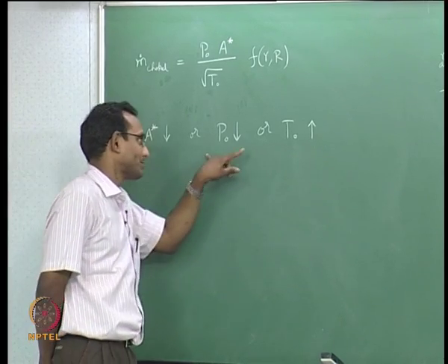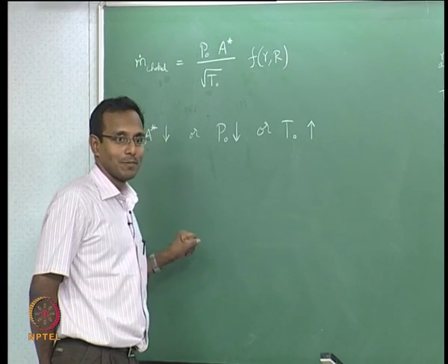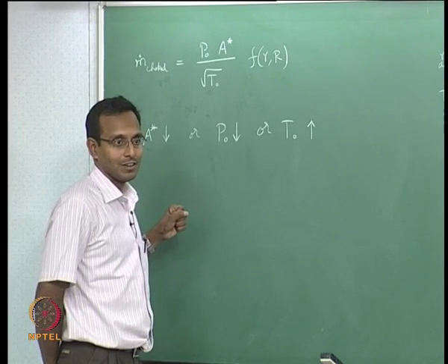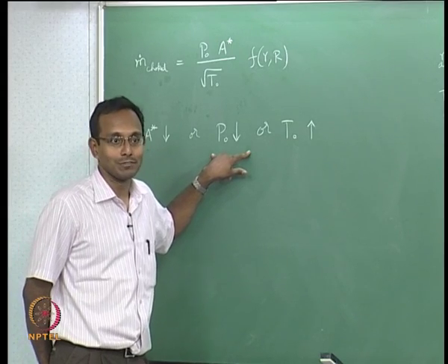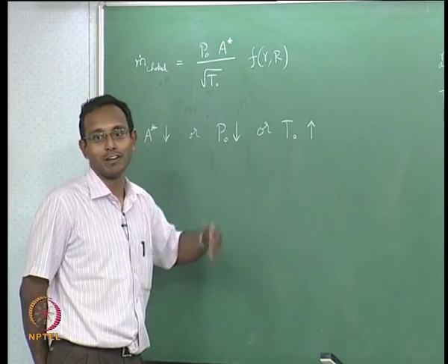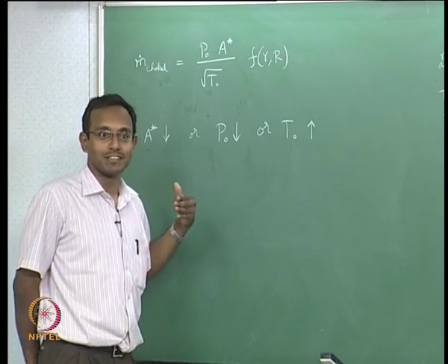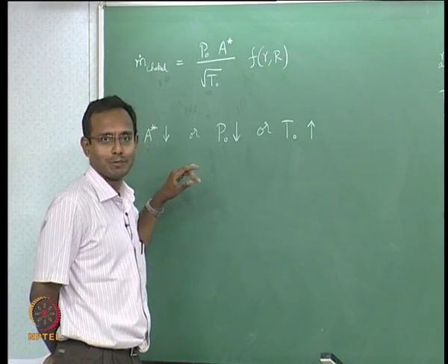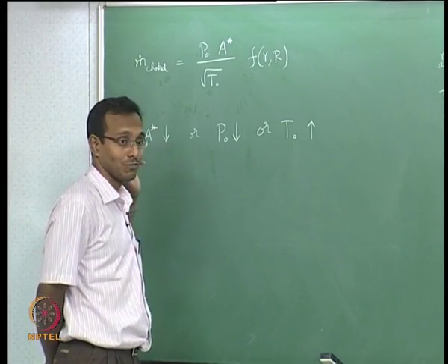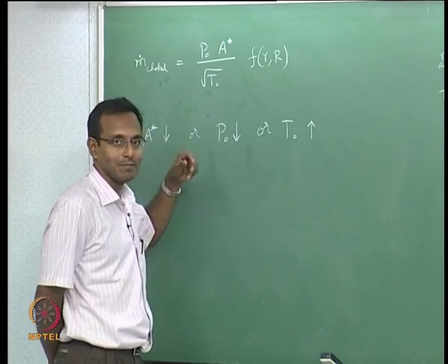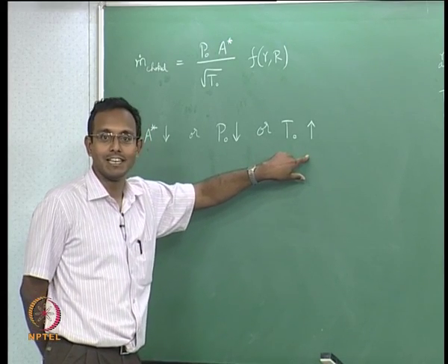Okay, so it can be introduced in thinking about that way, or I can think about some extra mixing happening. Okay, or some other crazy geometry that there is more drag in the flow. I put some protrusions inside my duct, and that is going to cause P naught loss. Okay, or maybe there is a shock forming inside, that is going to have P naught loss. Lot of P naught loss mechanisms inside. They are all going to take the flow towards choking condition eventually. Okay, I am thinking about a flow through a duct still. Okay, and in the middle I am having some P naught loss mechanisms. Or I can heat the gas, and that will take you to choking condition.